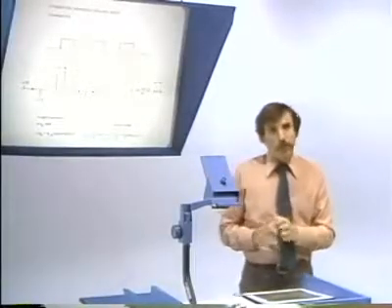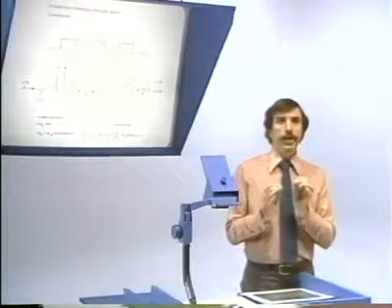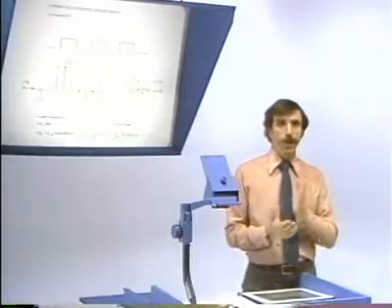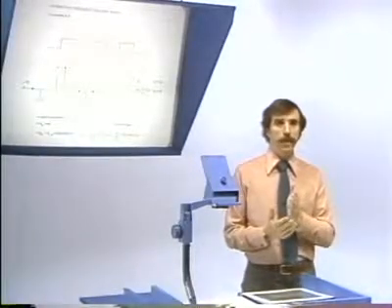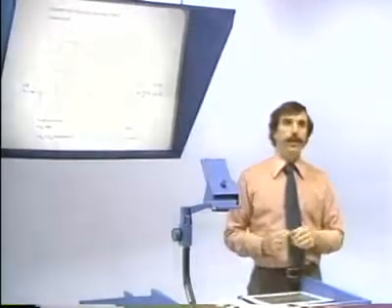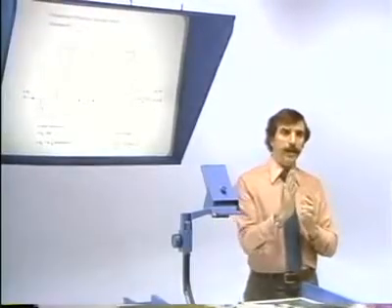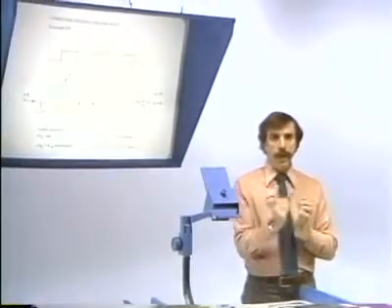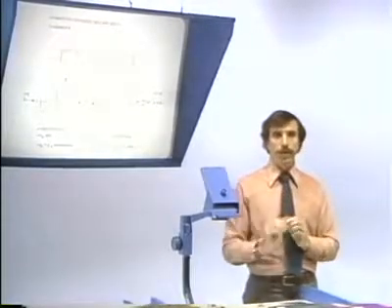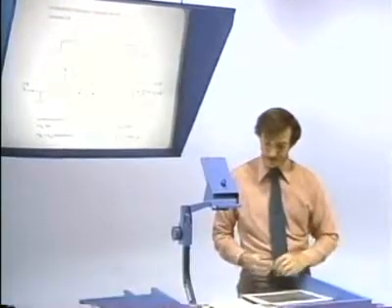Furthermore, in the two examples I've shown here, in both cases the signal is odd harmonic. In other words, for even values of k, the coefficients are equal to 0. Although I won't justify that here, that's a consequence of the fact that the symmetry is exactly about half a period. And if you made the on time of the square wave different in relation to the off time, then that property would also disappear.